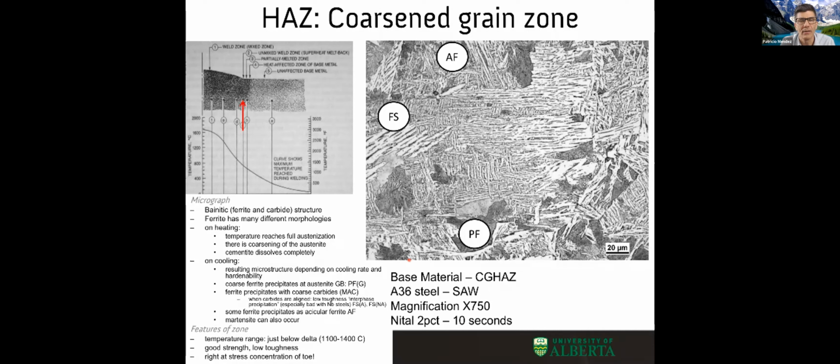And one of the examples we discussed on Thursday had two CCTs, one in a dashed line, one in a full line, showing that the one that corresponded to higher austenitization temperatures had a bigger grain size and was more hardenable.